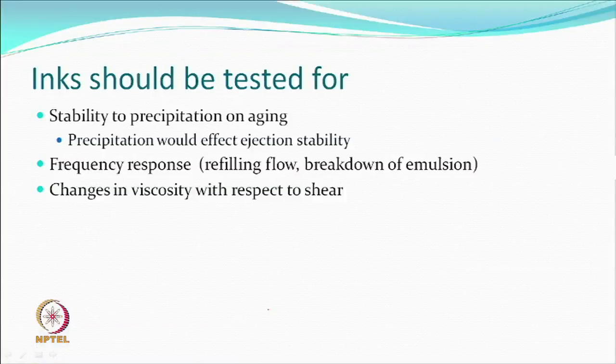So, these inks obviously will be tested for stability to precipitation on aging. They will be using tests. Then frequency response. Whether you have continuous jet printing or drop on demand, the frequency is different. When you talk about kilohertz, you understand what it means. In such a small time, you are ejecting so fast. How does the liquid respond?